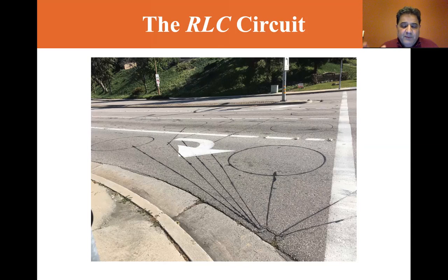The metal of the car represents a magnetic material which alters the magnetic field passing through the loop. So the eddy currents induced in the metal car produce additional magnetic field lines that pass through the inductance loop. So the change in inductance L of the loop changes its natural frequency of oscillation, and the control electronics detect this change. It sends a signal to change the light from red to green.